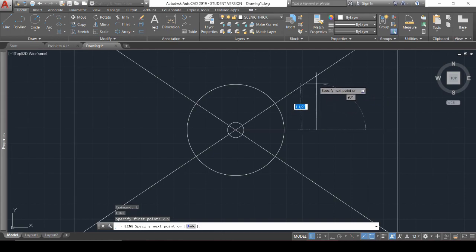If I wanted to specify an angle, I could tab over so that the degrees is highlighted, and I wanted 90 for this, but I could do 45 if I wanted. It's whatever you set. So if you click and specify a point and that was a mistake, you can hit U, enter, and it goes back. And now I can specify my angle again, tab 90, and right click to complete.